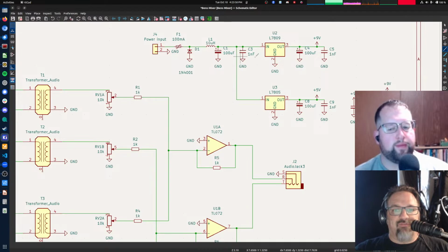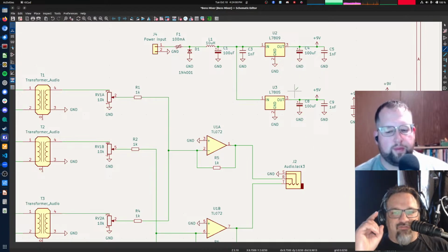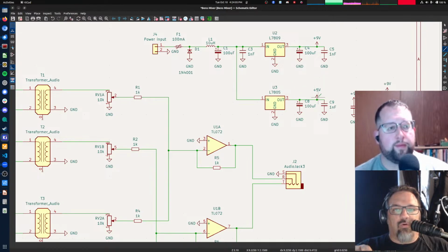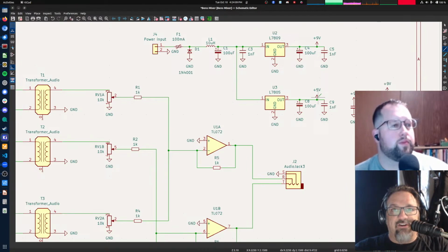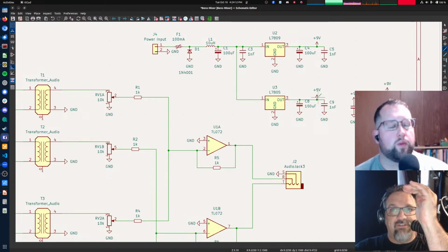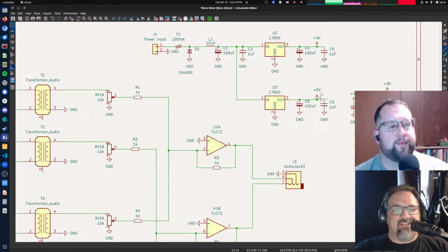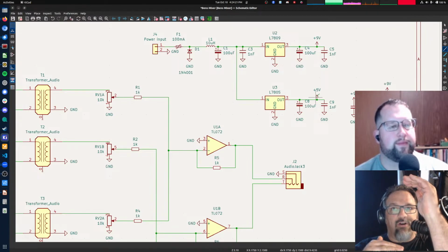So we have one input filtering and then 2 output regulators, one that creates 9 volts, one that creates 5 volts, and then ground. And those are our power supplies. There are various reasons that's not the preferred way to do it, because now your middle voltage is not perfectly centered between 5 volts and ground. Especially if you start dropping input voltage here, your 9 volts will become 8 volts, which gets even closer to here. And so your middle voltage is not actually the middle.